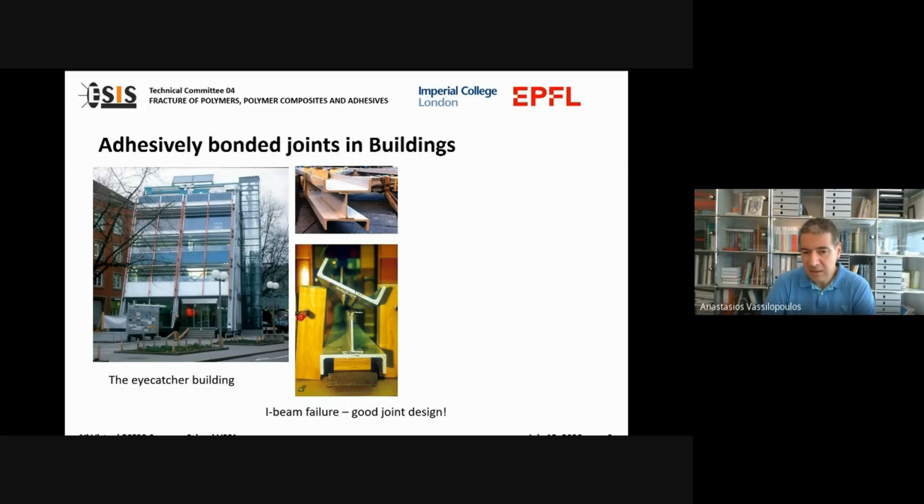And we see again, this is a result of the 3-point bending test of this element. And here is, by the way, a typical example of good joining technique. For those of you that read the papers from Hart-Smith, his first argument was that the joint should be the point where the failure does not happen in a connection. And here we see that the failure didn't happen in the bond line, but happened in the flange of this. We can call it an artificial I-beam.